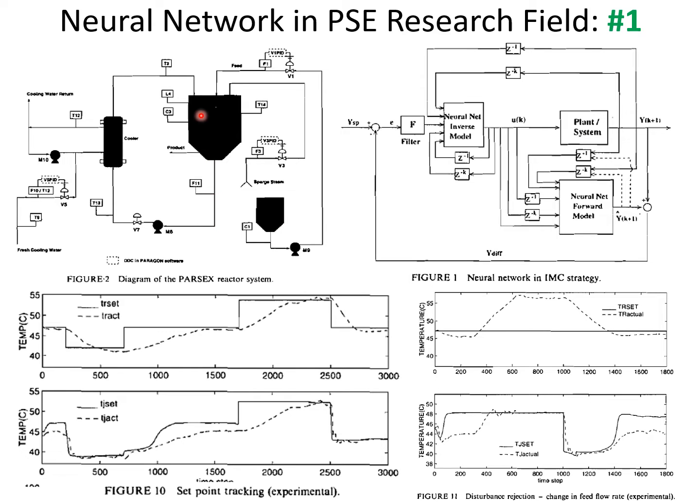So this is basically the pilot plant, a simulated reactor, where you don't have a real reaction, but the real reaction is being simulated by equation. We have steam coming in that will simulate the exothermic reaction. We calculate the exothermic reaction, how much heat is coming in, and that is implemented online through the amount of steam that gives the amount of heat based on whatever simulated reaction you've got. And then we do the cooling outside, with an external cooler system, to control the temperature inside the system.